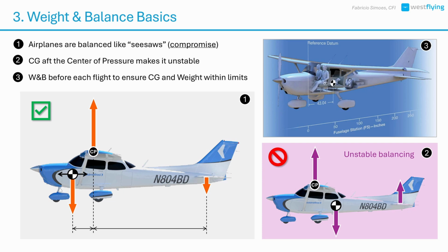If the elevator stalls, for example, the nose of the airplane will naturally go down. The airplane will gain airspeed, airflow over the wings and elevator will increase, and then the forces in the elevator will increase, pushing the nose up or level again.